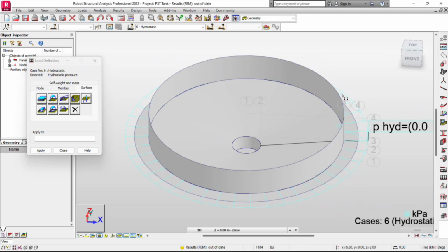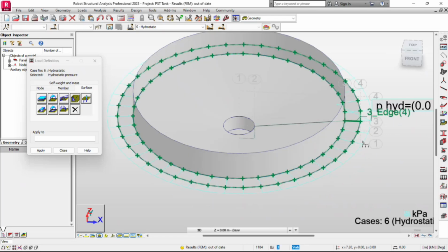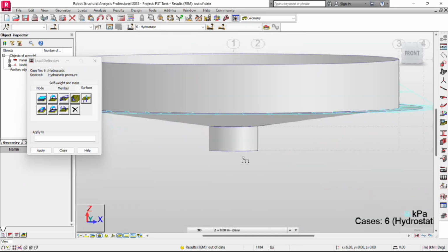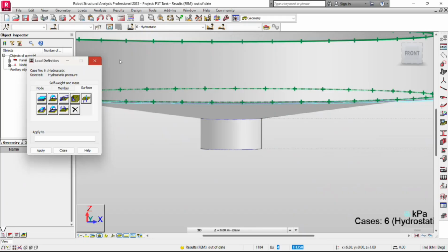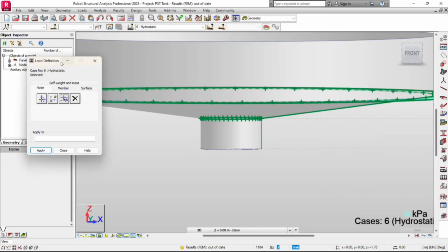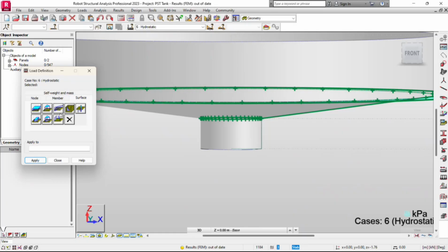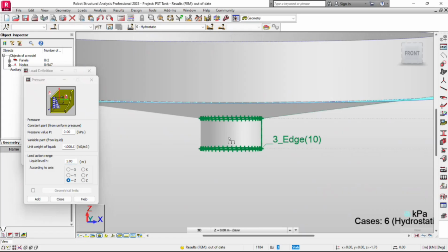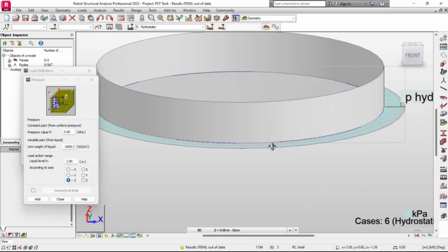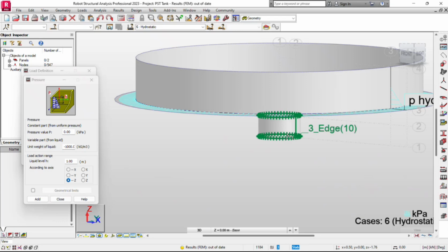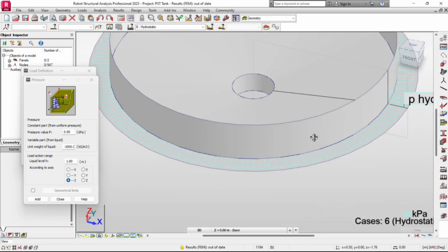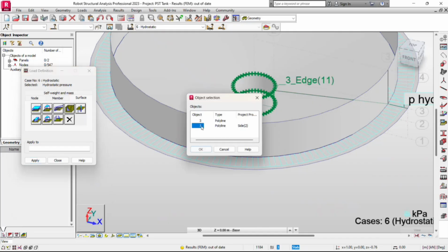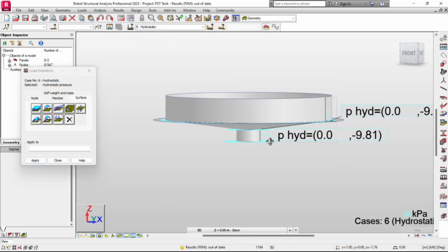And then on the base, this hydrostatic pressure isn't just applied on this wall because we also have a hopper over there, right? So it has to be applied also here. The same item. I should have applied both, but now I'm going to create another one. It's still the same, negative 1000 by 1, and then just choose this element over here. Just hit add first and then select that area over there and then just choose side 2. Okay, there you have it.